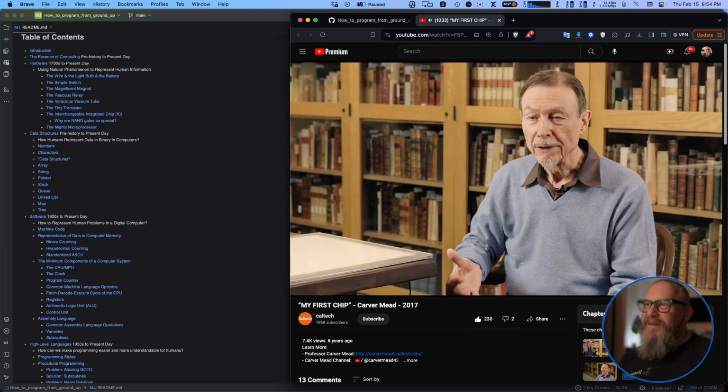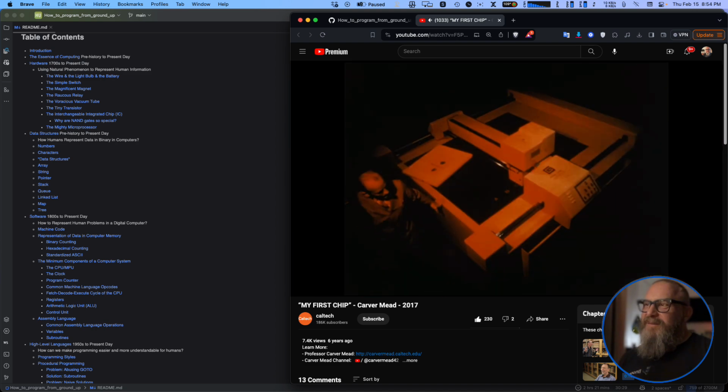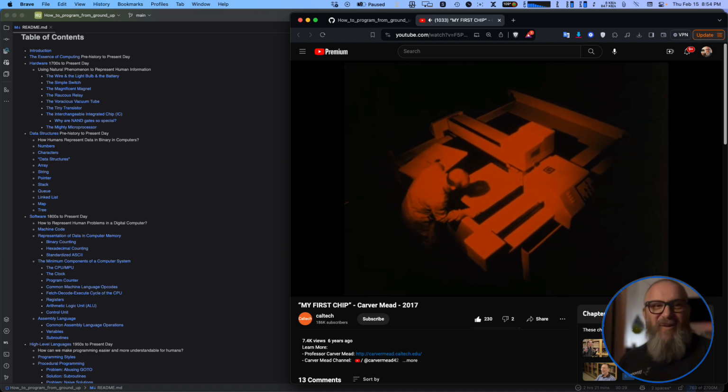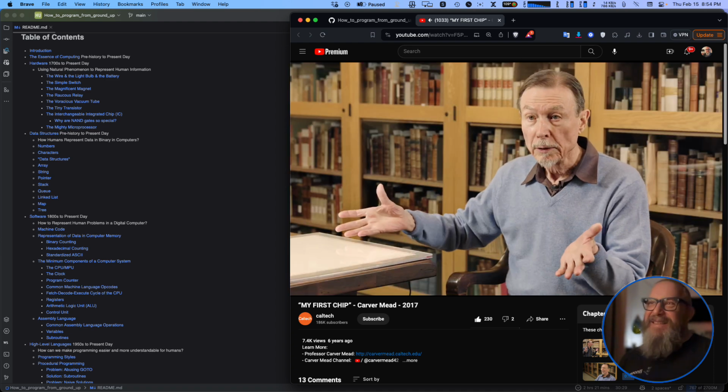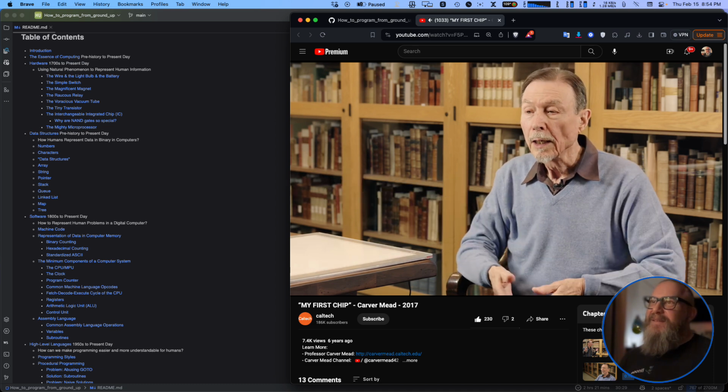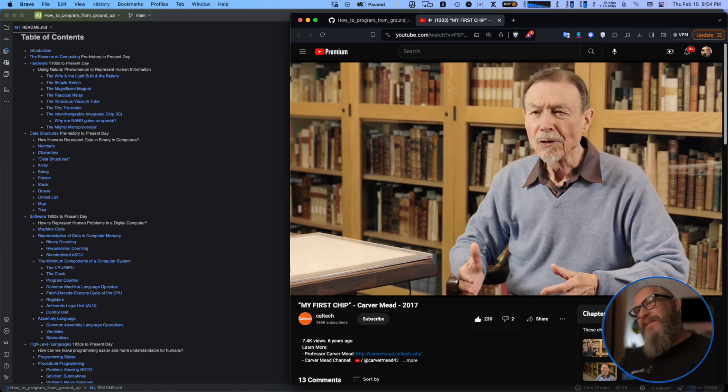Well, I can't afford a Gerber plotter either, and it was a big thing. You had to have it in a darkroom, of course, because what you put down was Mylar that had photographic emulsion on it. It was basically a great big photographic negative. And then you drew one all in the dark. When it was done, you ran it through a photographic development process. So I couldn't afford to do that, and I couldn't have the time to do all that.